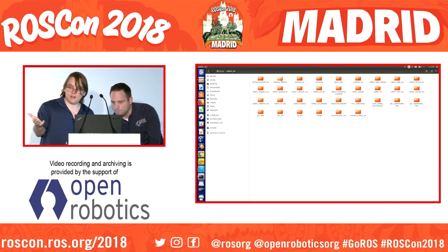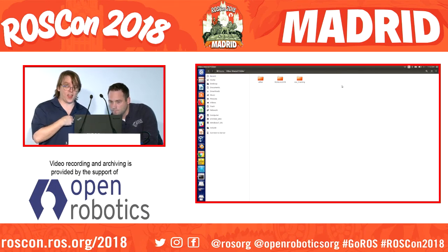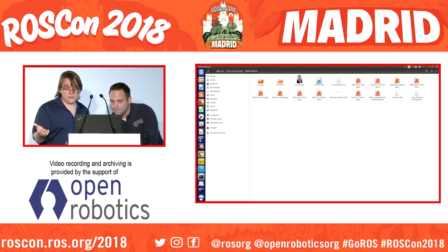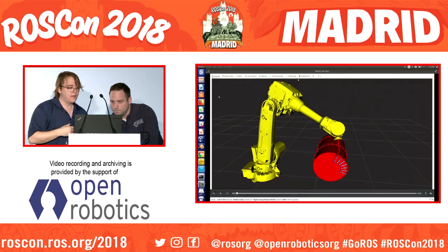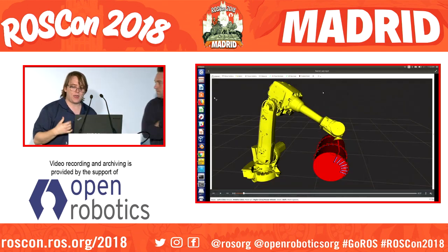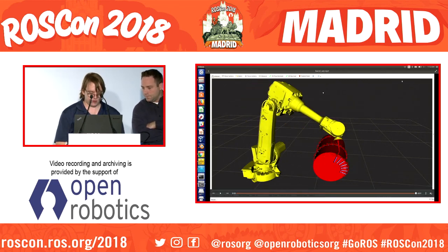But it still has its own problems, right? Discretization doesn't work well in high dimensions, and you end up with little quirks of motion planning, where if you only search here, here, and here, your robot path will be moving along, and then you'll see a snap that happens. There are ways to fix it, but that's where doing something like TrajOpt actually makes a lot of sense. So we actually need to go to the next video here.